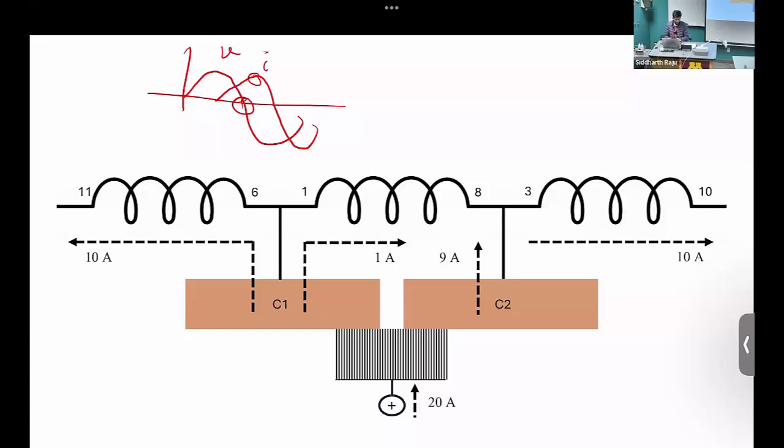So here in this case, our coil is a mix of inductive and resistive components. The resistive part is not trivial. When you have just the coil alone, the resistance is trivial. But in this case, the coil is shorting through the brush, and the brush has quite a bit of resistance. So in some way, the brush aids in your commutation process. If you have a graphite brush, that's fine; if you put a copper brush, it gets a little bit tricky because the resistance is very small, so it acts more as inductive. So it gets even delayed further.